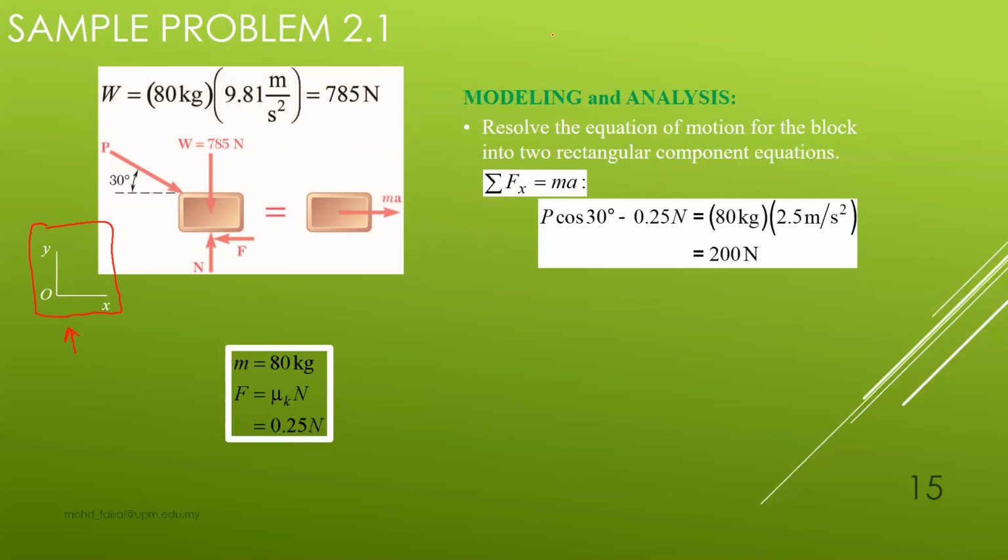For statics, when you learn statics, what happens is you will have the summation of forces equal to 0. However, for dynamics, the summation of forces is not equal to 0. It will have a certain value. For dynamics, remember, it will not equal 0 because dynamics means something that is moving. Okay, first we resolve the forces in the x direction, F = MA. Actually, this one should be M a_x.